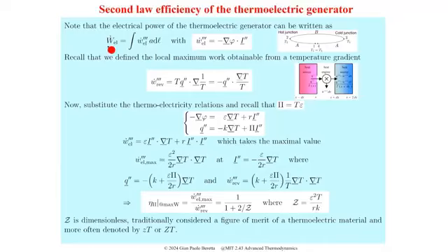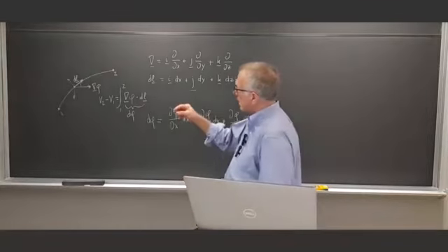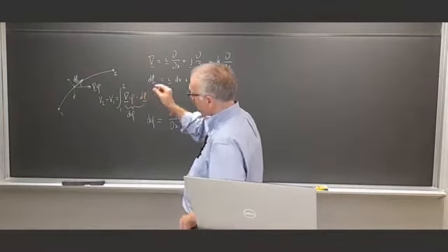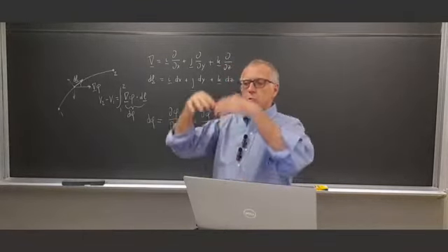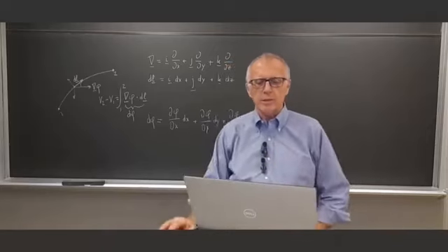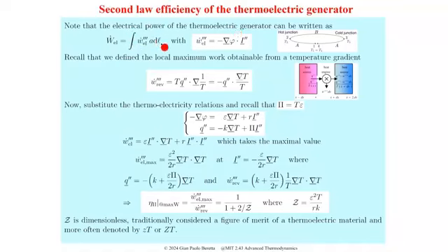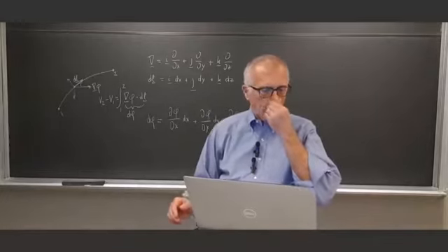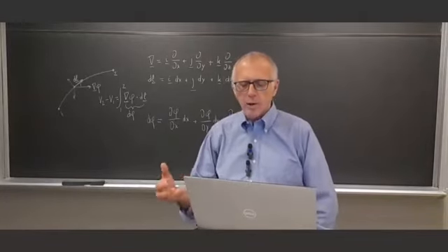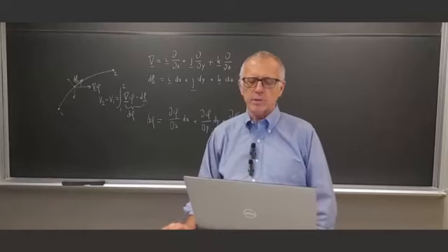If you accept that you can rewrite the power of the thermoelectric generator that we have developed in the previous slides as an integral of what happens locally, as if everywhere in the wire there is something that is the local contribution to the overall effect, you integrate that local contribution over the entire distance, and you get the overall effect. In a sense, this is a power density, the electrical, useful power density of your device.